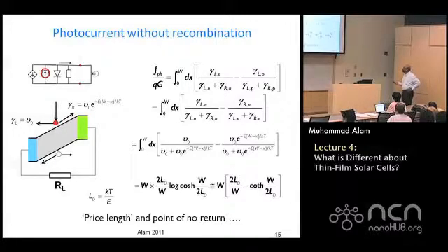What this is all about is essentially that if you are close to this region where electrons can escape, there will be a loss of a certain number of electrons that will not come out through the right contact, and so you will have a reduction in current. Your current cannot be voltage independent, because as I am pushing this voltage up and up, biasing it, the fraction that will begin to go through the other contact, the wrong contact, will increase.